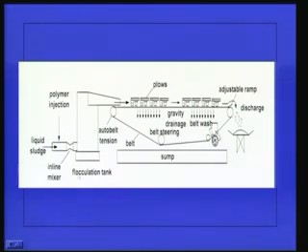Here we can see that the liquid sludge is coming, we are adding some polymers and that is coming here, it is moving through the belt, and because of this gravity drainage is taking place. So water is getting removed, and this portion is meant for belt washing. So as it moves, the sludge will be getting dewatered and here we get more concentrated sludge.